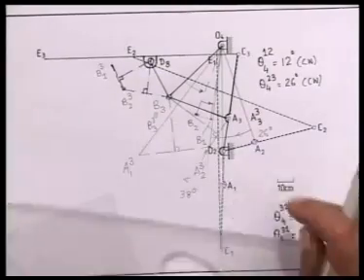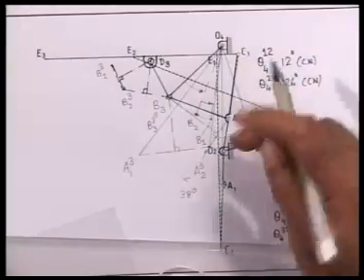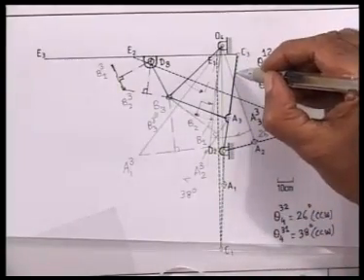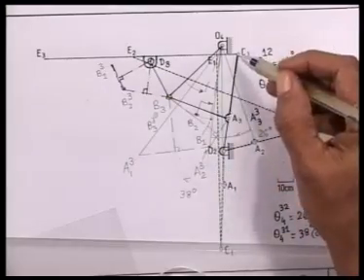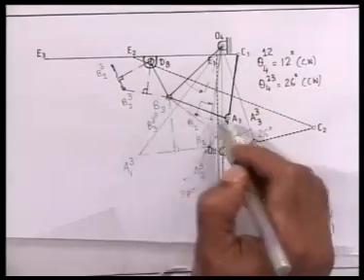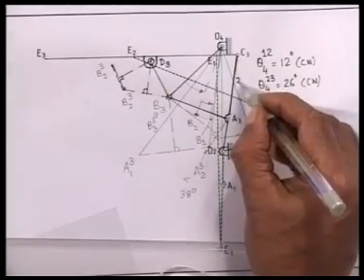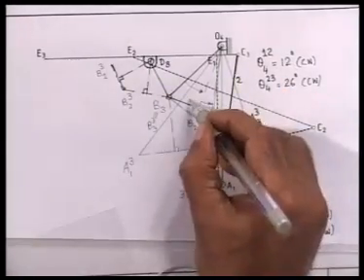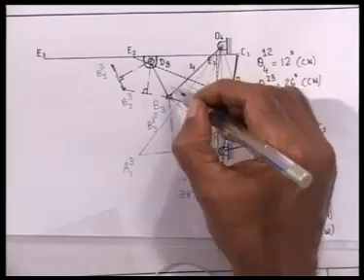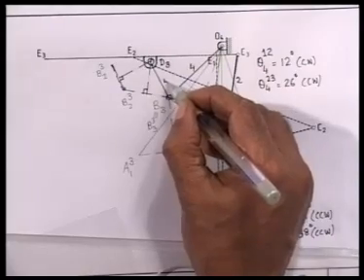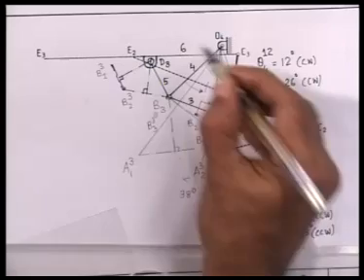So we get by this firm line the representation of the entire mechanism. O2, A3 is one link, so let me say this is link number 2, A3, B3 is link number 3, O4, B3 is link number 4, B3, D3 is link number 5, and the door board C3, E3 is link number 6.